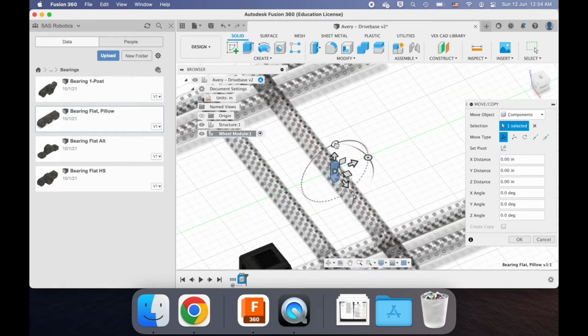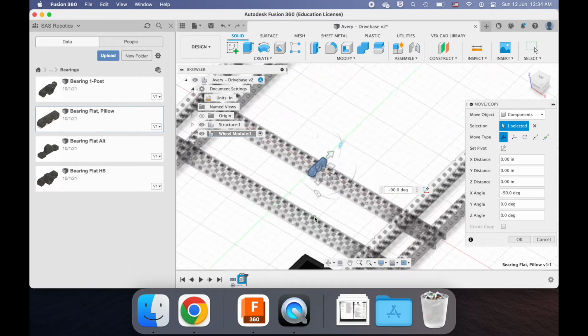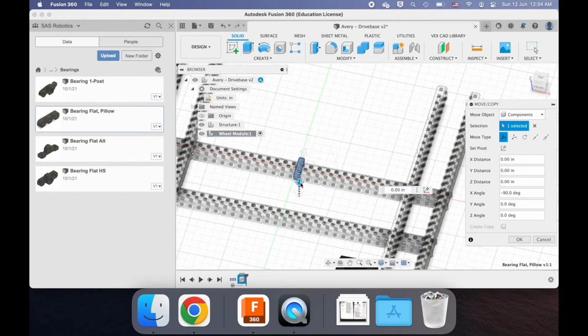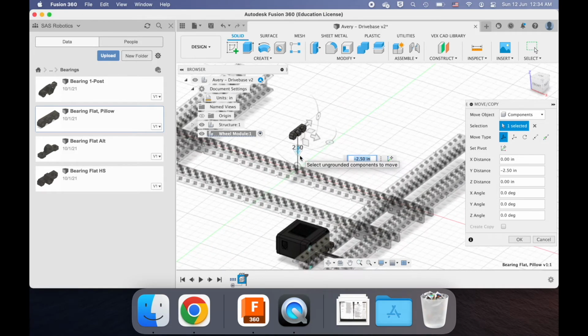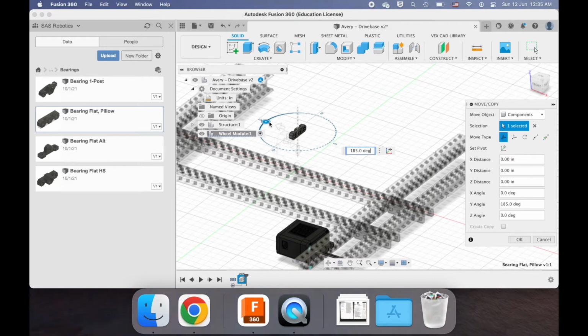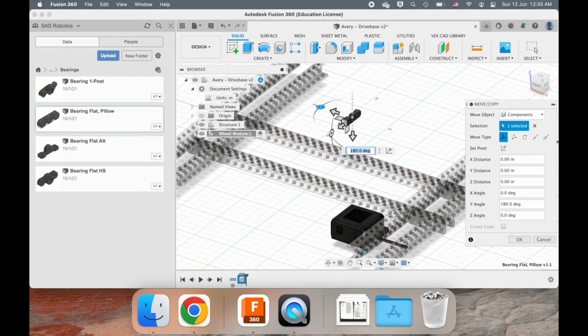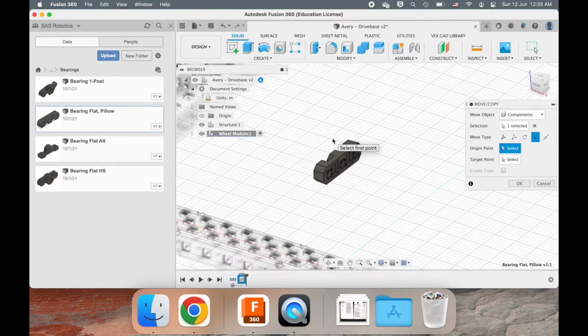So it's a general rule that you always support every axle in 2 locations. Okay, and that includes the usage of bearings in 2 locations. You can't just simply have the axle go through 2 C channels, but there's only 1 bearing on one of the sides, right? That doesn't work so well.